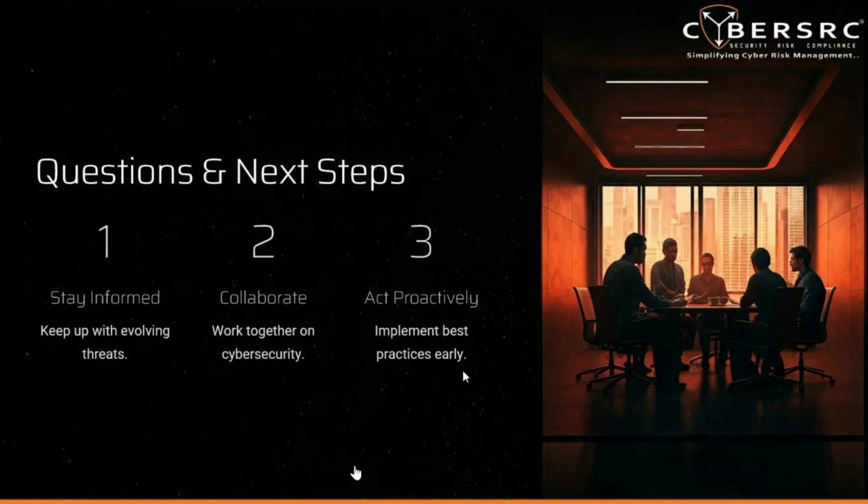So again, about the legacy system, what are the most effective methods to implement network segmentation in ICS environments? To implement proper network segmentation, you can use network devices such as firewalls, switches, and routers. Industrial firewalls and industrial switches often have controls and policies to implement proper network segmentation. You can also use data diodes to ensure that there is only one-way traffic flow. So these are some principles that you can use to perform proper network segmentation.